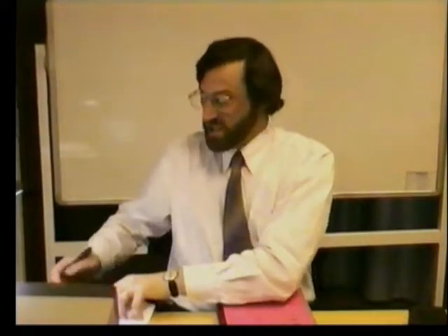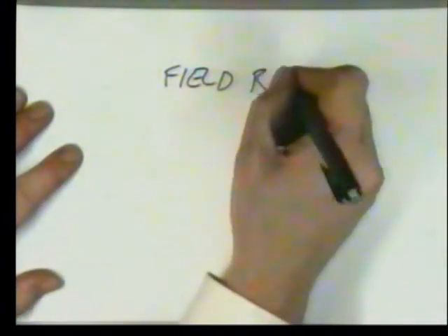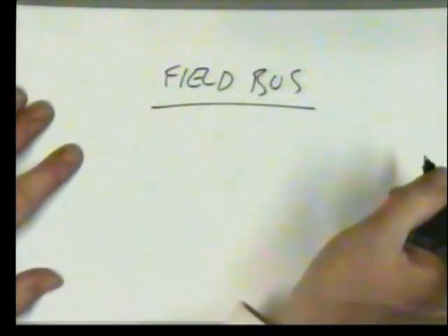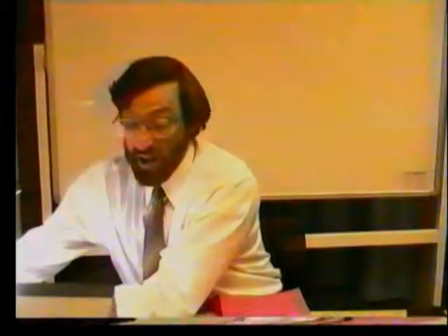So in process industries, there has been developed over the many years a whole family of LANs, generally known as field bus technology. Field bus. Every manufacturer has come out with their own standard for it, and they have been sitting on an international standards body for over 15 years trying to agree a common standard.